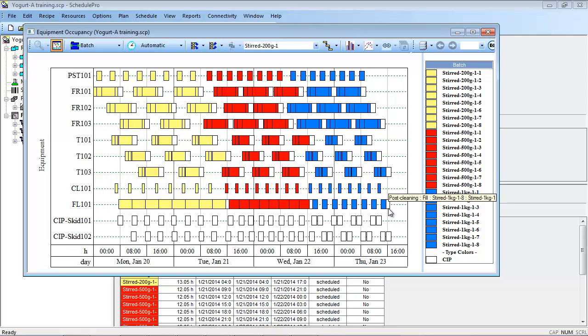The cleaning activities associated with the fermentation and storage procedures in every batch are also shown in white, regardless of which campaign they are associated with. This was accomplished by specifying that cleaning operations within each recipe should be assigned to the CIP operation type, and the default style option for the EOC should be overridden. For information on how to do this, please refer to the README file for this example.